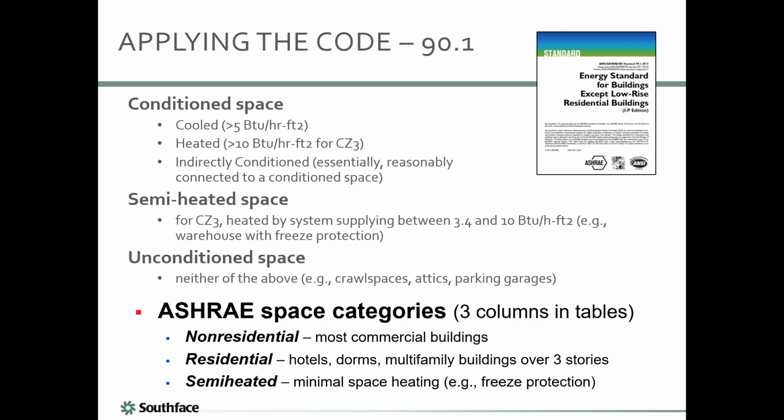ASHRAE also has one extra thing that the other code doesn't have, which is a semi-heated space. And we'll talk more about that, but I would really think a better name for that would be freeze protected. And then I didn't mention, but if it's an indirectly conditioned space, that means the space is inside the thermal envelope. That's still conditioned space. Examples of unconditioned spaces are things like a vented attic space or an open air crawl space or an open air parking garage or something like that.